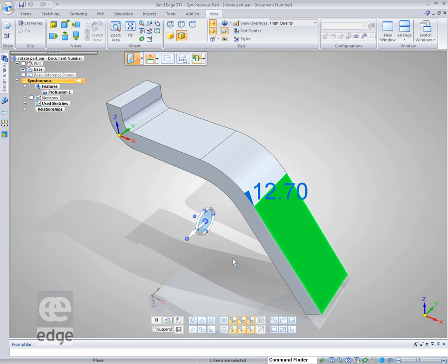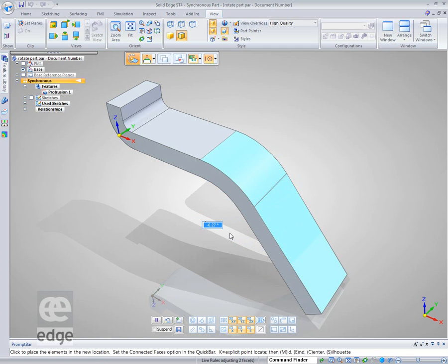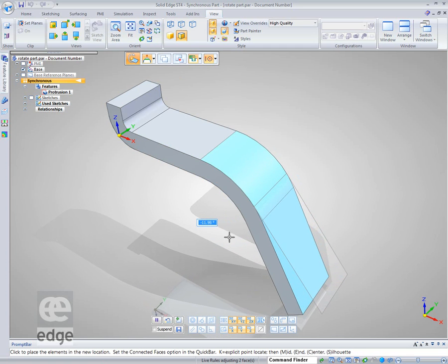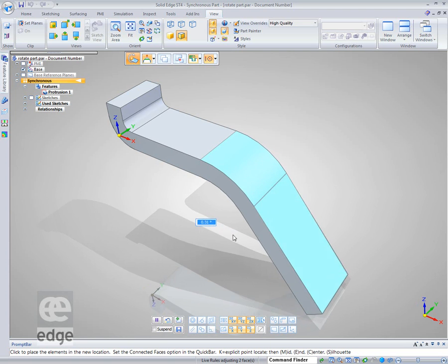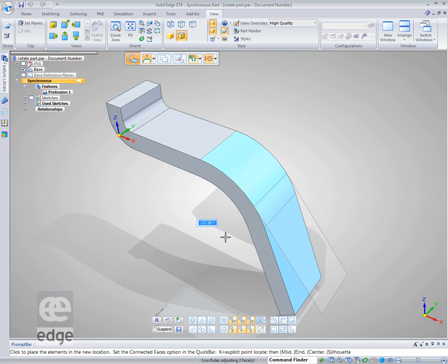Now, what we've seen here is that the steering wheel is oriented not the way I want it. I wanted the plane of the steering wheel to be coincident with the plane of that face. So all I have to do is hold the shift key down and click on the surface there, and it snaps it round. I actually did that deliberately so we got that effect. Now if I select the torus, I can rotate. I'll do this slowly so you can see the screen update. And I'm simply changing the shape. I'm bending that thing around that center point.